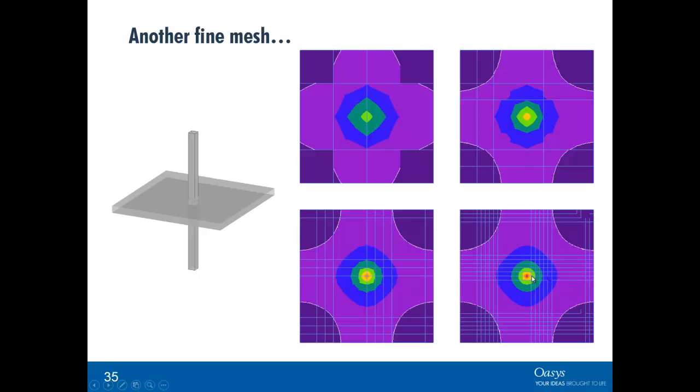And this is a mathematical anomaly in FE. You've got two-dimensional slab shell elements, and they are two-dimensional. They just have width and length, supported on a one-dimensional column. It's just a point. The finer the mesh, the higher that peak moment will get in the analysis.